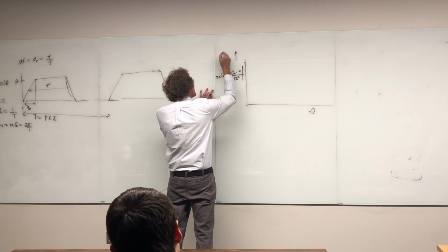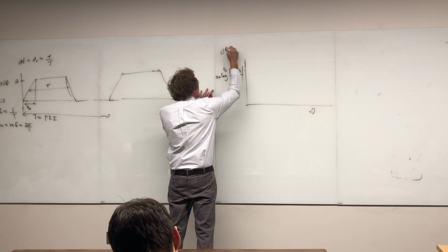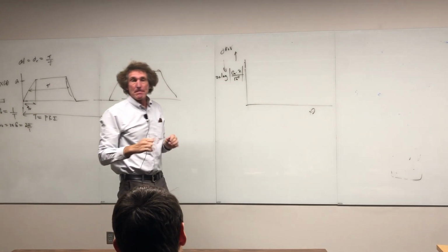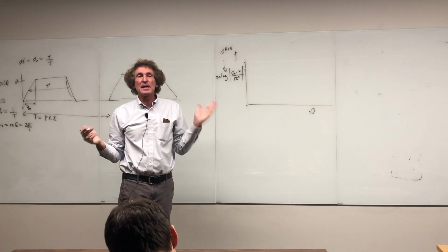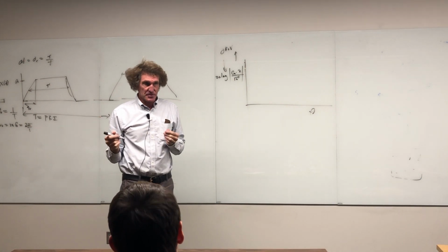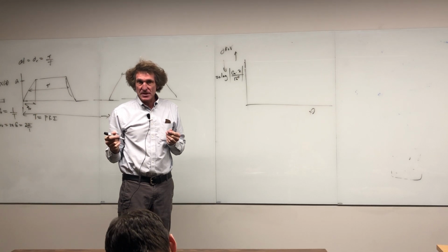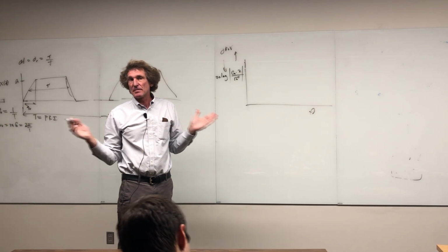That means this is going to be in dB microvolts. If you have something that's a regular voltage, you divide it by 10 to the minus 6. That's the level of microvolts. And then you take 2 times the magnitude of this.